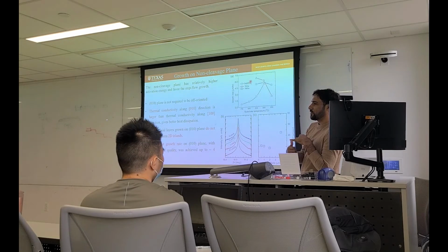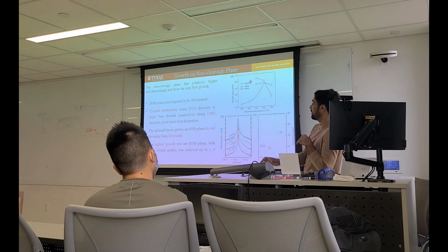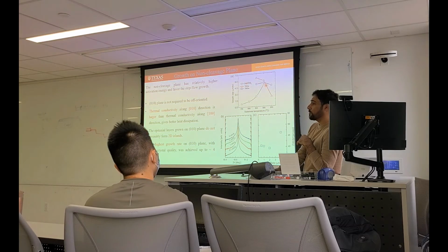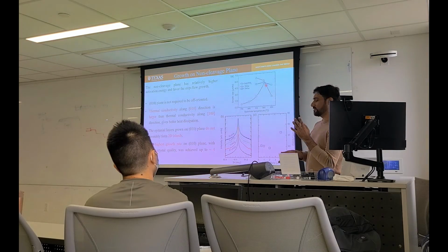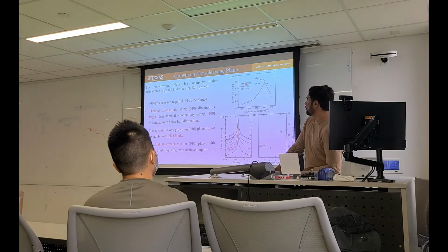You can even keep it at 22 degree, and you can control your bubbler pressure. But for this source, you need to heat it above 100 degrees centigrade. And it is really challenging. You need to wrap your whole line to the reactor, and if your temperature is not achieved, then it will be blocked because of sublimation and condensation issues. So it is not used now.